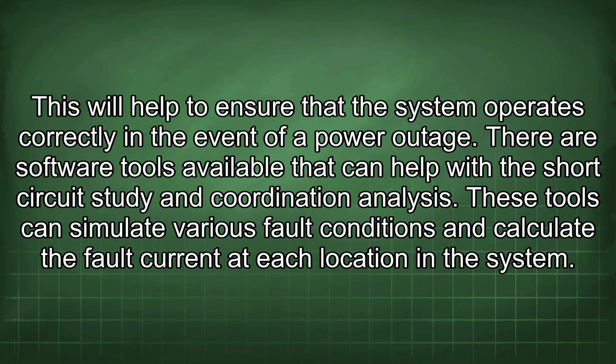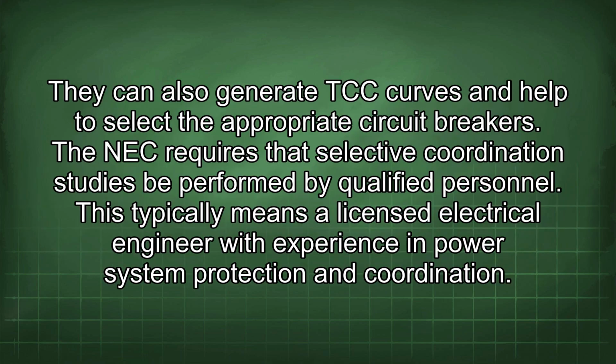There are software tools available that can help with the short circuit study and coordination analysis. These tools can simulate various fault conditions and calculate the fault current at each location in the system. They can also generate TCC curves and help to select the appropriate circuit breakers. The NEC requires that selective coordination studies be performed by qualified personnel. This typically means a licensed electrical engineer with experience in power system protection and coordination.